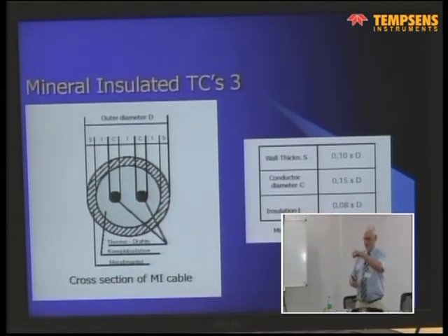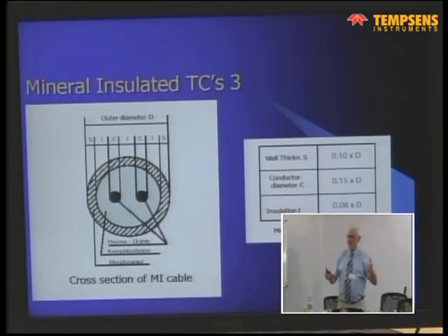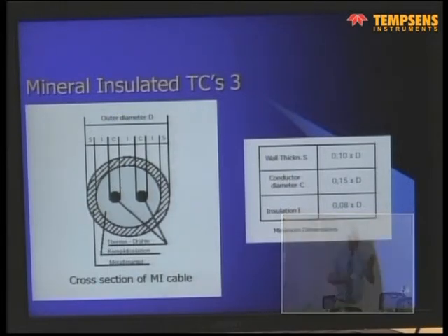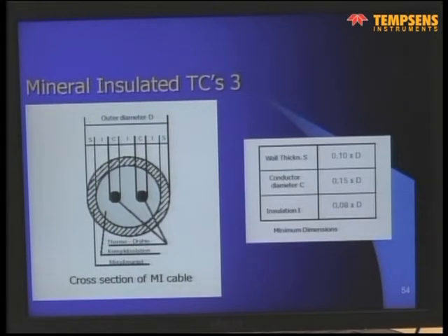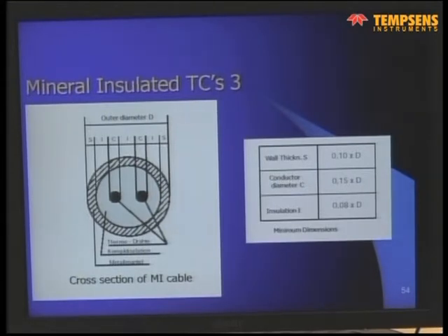First in rollers to reduce the diameter up to 10 millimeters, and then you draw it through what is called stones. Yeah, through the die. Yes, through the die. In Europe they are called stones. Okay, up to the desired millimeter. If it is 8 millimeter or 6 millimeter in diameter, even 4.5.